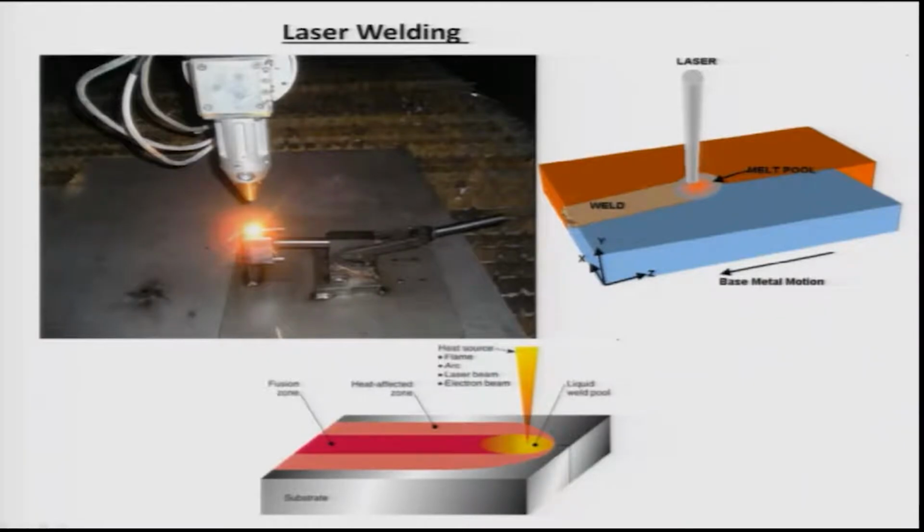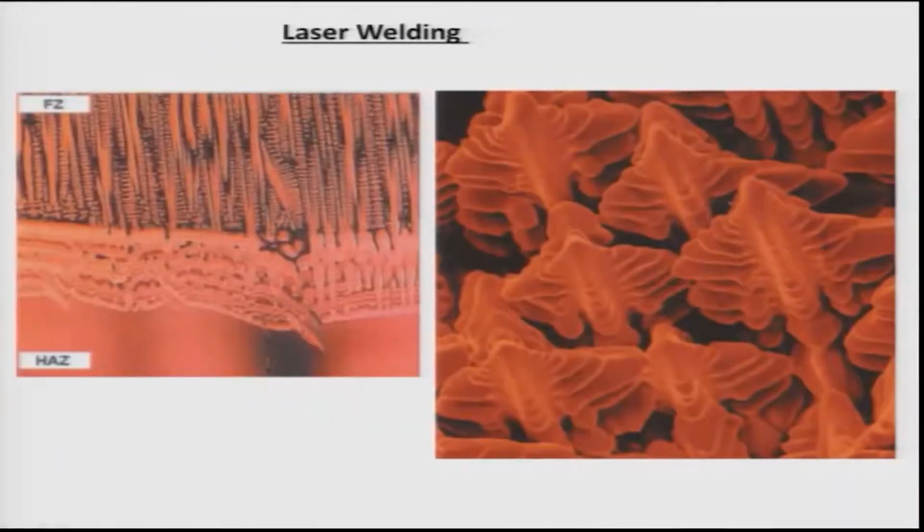So that's why the growth of these nucleating phases, which are forming at the two joining surfaces, is the most important aspect. All these industrially important processes require you to understand solidification. You see here the different zones of the weld. This is the fusion zone, in which you form certain geometrically important features known as dendrites.